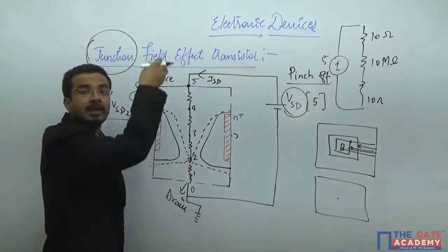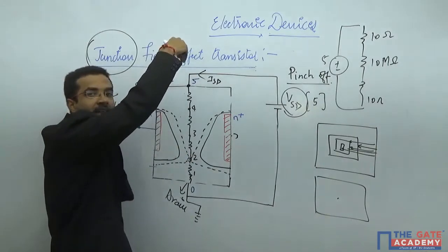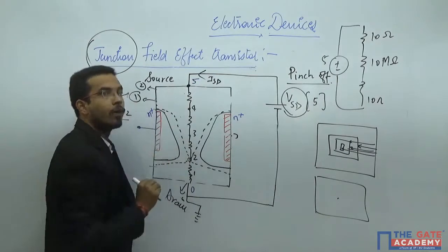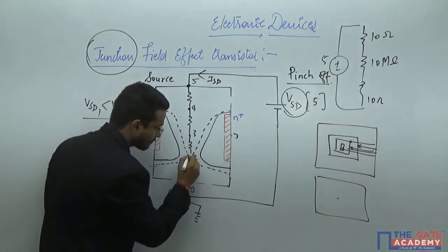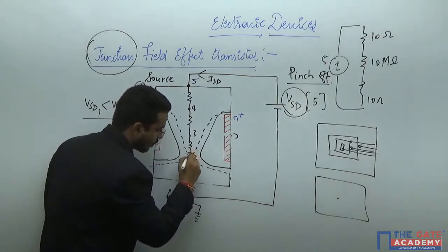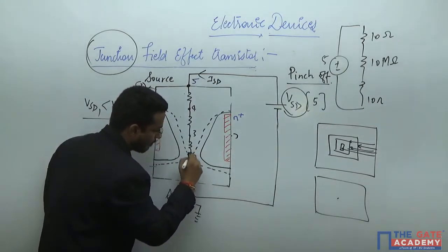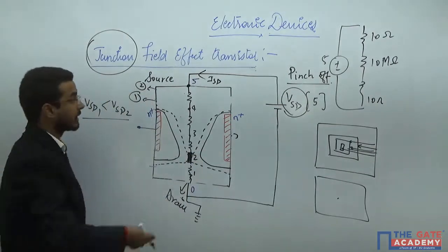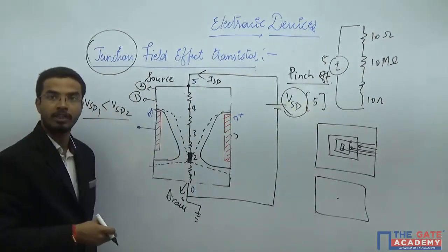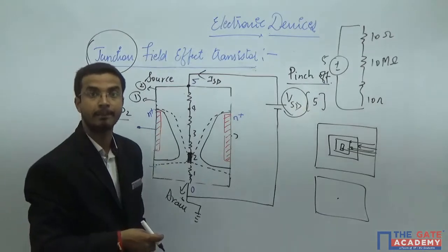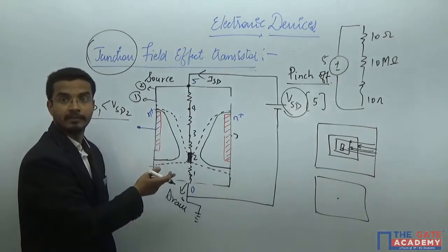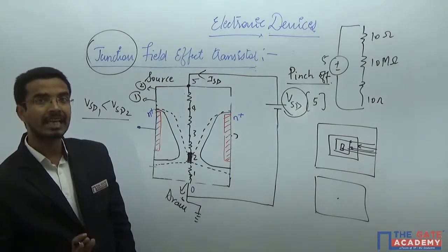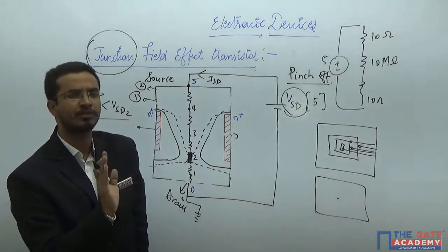That channel means the path for the majority charge carriers to flow from the upper body to the lower body. At this time, these will touch each other, and this phenomenon of touching, where you are not getting the gradual decrement of the voltage throughout the device, is known as pinch off. And this will be the actual pinch off in the device. Because you have taken the practicality also, that means the current will not become zero now.